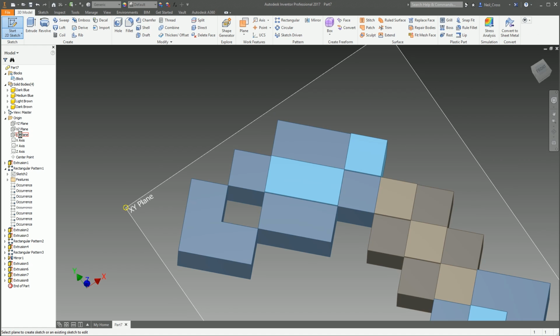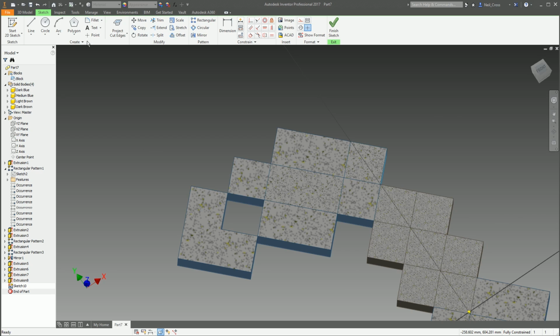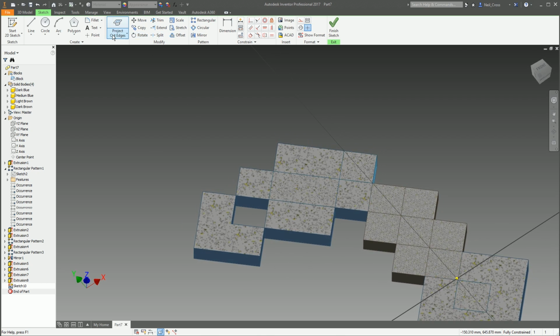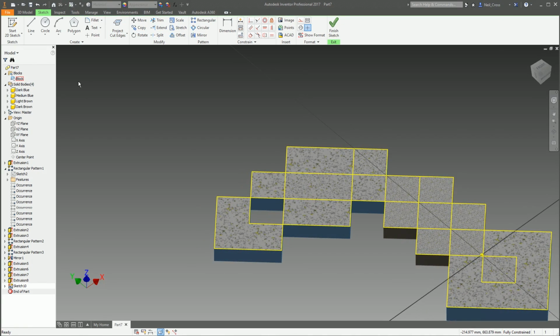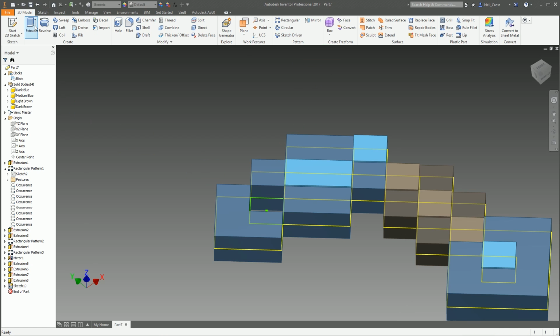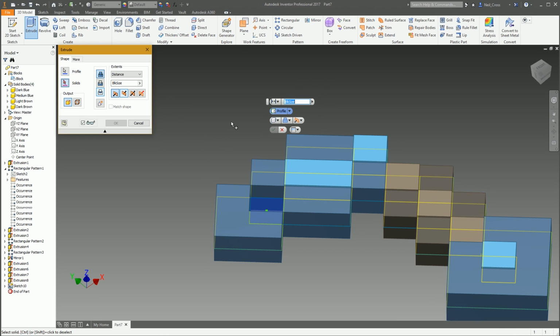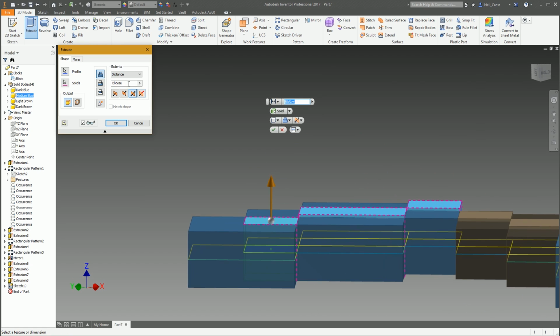That one there. So that was raised slightly higher than the other ones. So sketch in there, F7. I should probably stop saying F7. I think by this point you probably get the picture. And then place him in there. Okay, and extrude him. Solid. And there you go. Mid plane. And this one's +5, isn't it?